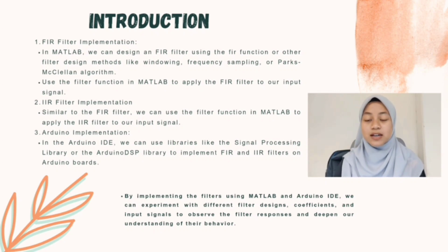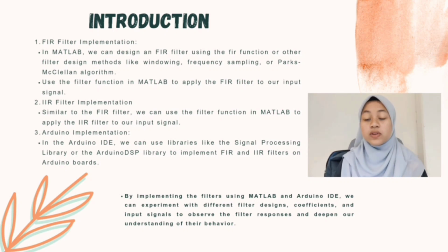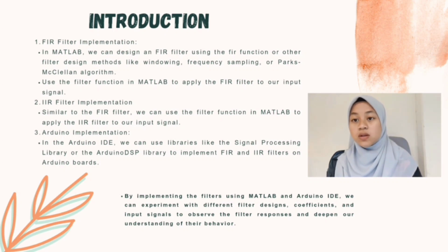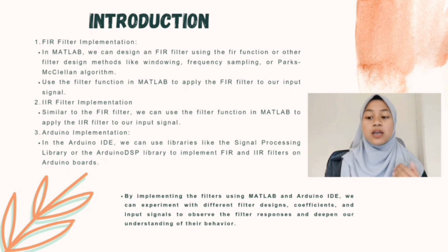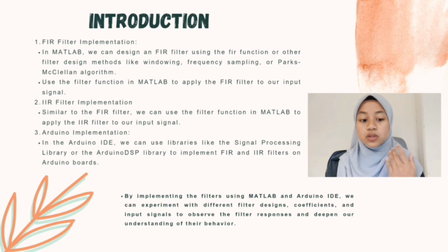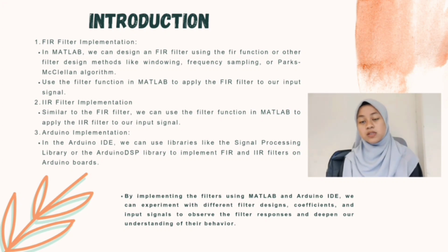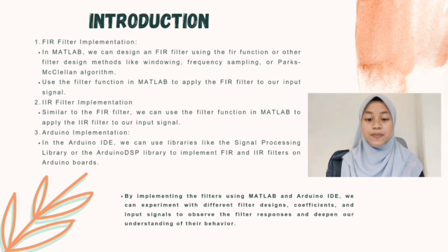Second, for the infinite impulse response, in filter implementation, similar to the finite impulse response, we can use the filter function in MATLAB that applies the infinite impulse response to our input signal. So the MATLAB freqz function can be used to visualize the frequency response of the infinite impulse response filter as well.